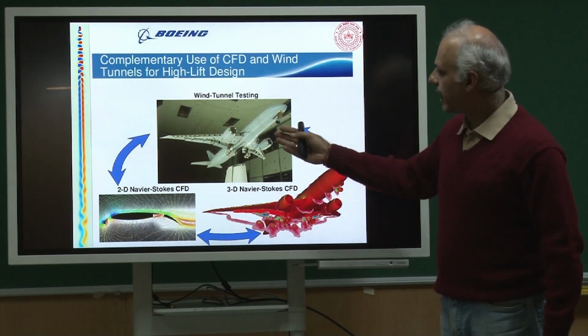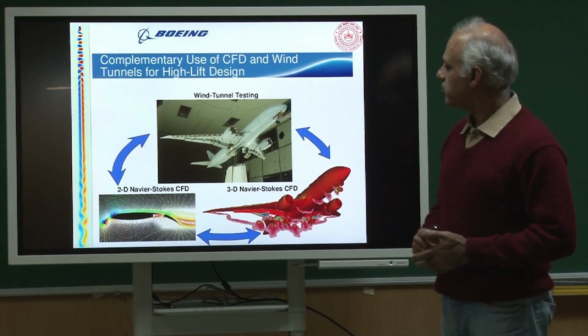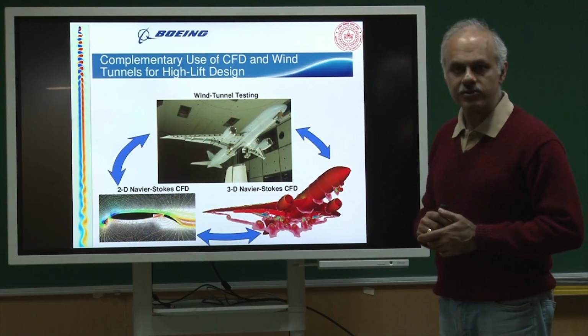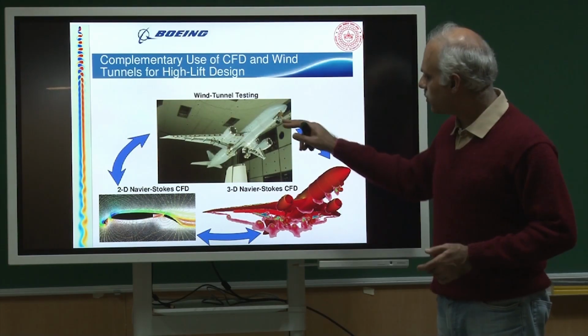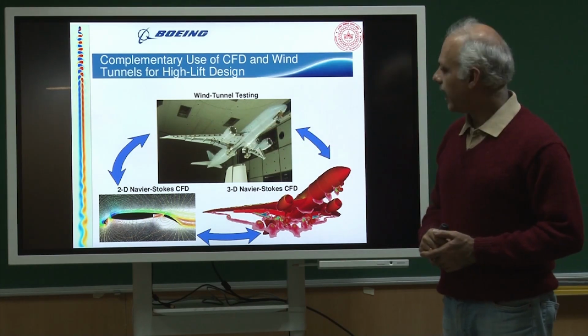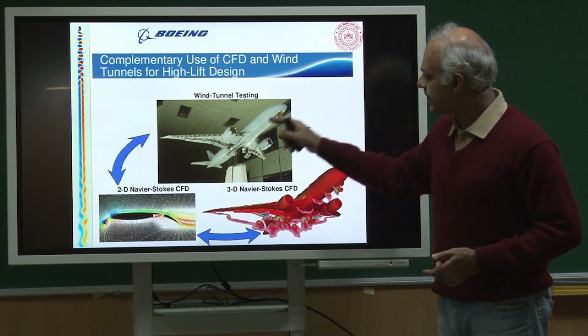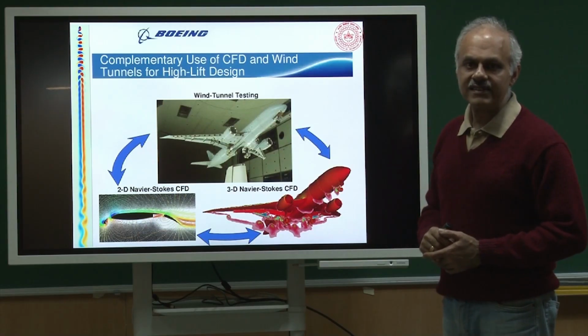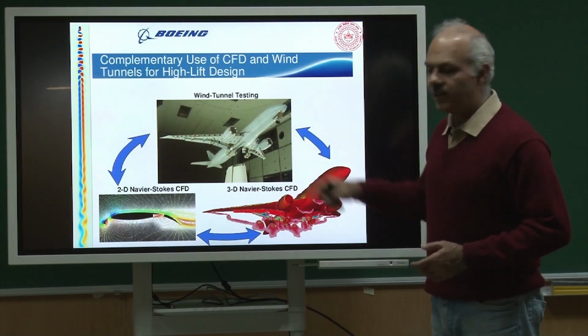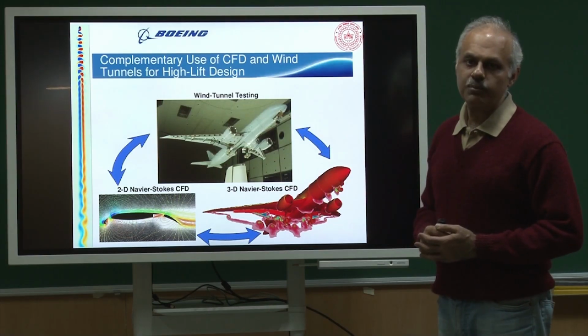A is to do some kind of wind tunnel testing. Those of you who are not familiar with wind tunnel testing, let me describe it to you. If I want to design an aircraft and put engines on it, I would like to know what is the drag, or the air resistance, faced by this aircraft, because that would decide the size of engines that I put in.